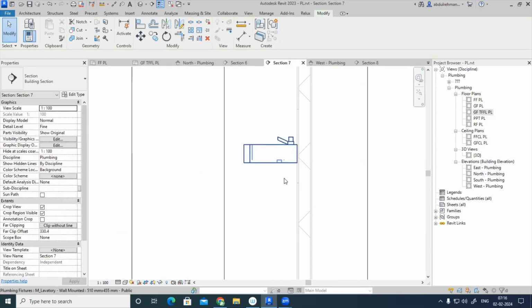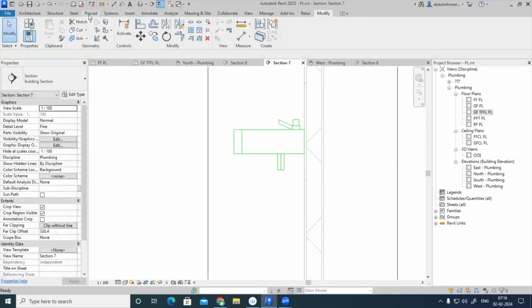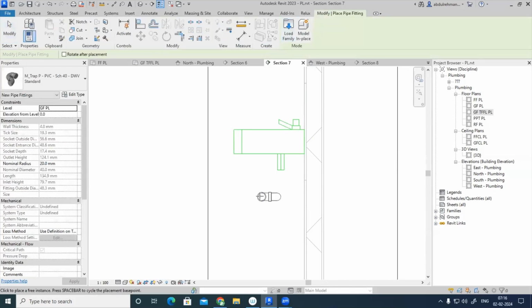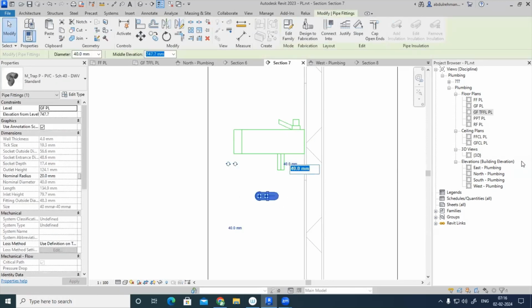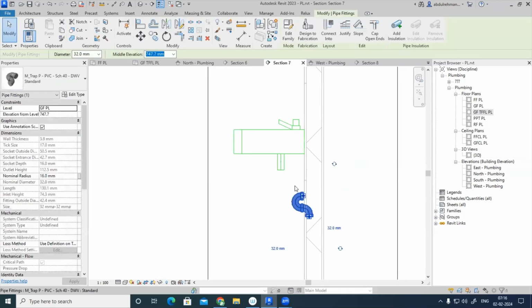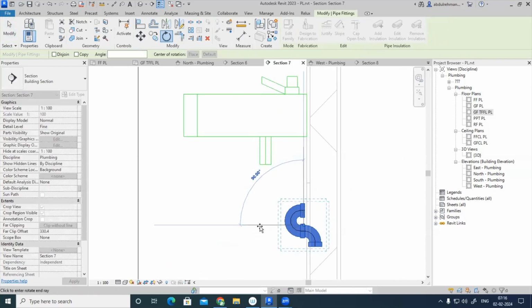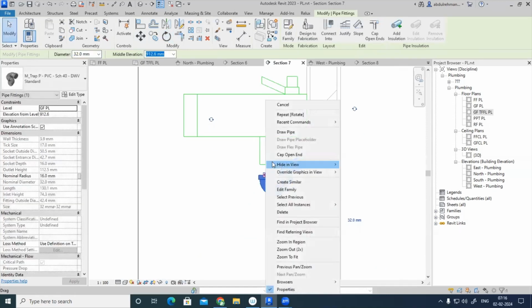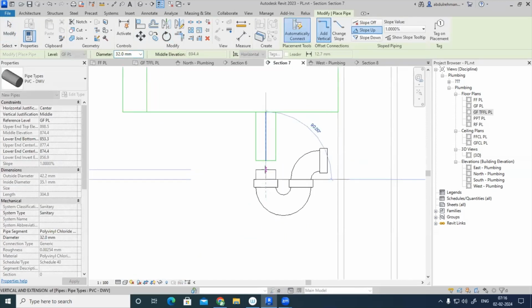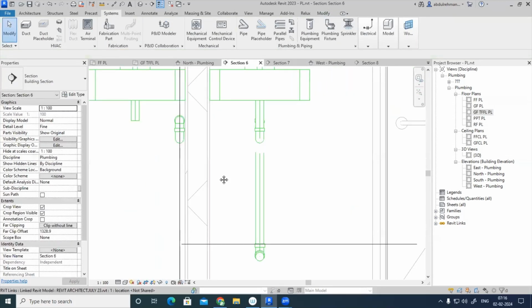Okay. So wash basin, 32 mm. From the systems, piping, trap, piping, fitting, trap, it is, let's say, 32 mm. Rotate this one, mirror it. Okay. And once again, you have to rotate that, with respect to that point, the 90 degree I'm rotating just to move it there. Make a small pipe. Instead of this, which one? U-trap or P-trap, we can try for bottle trap as well.